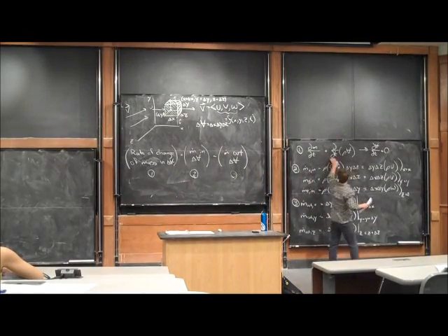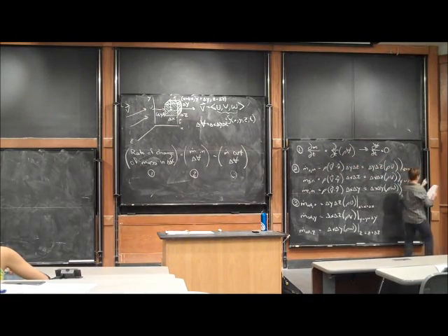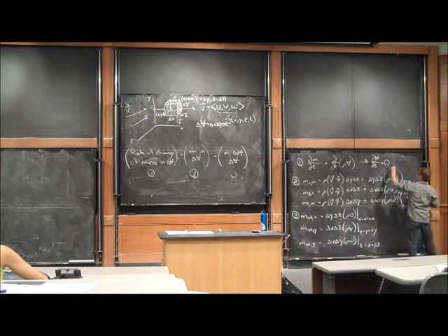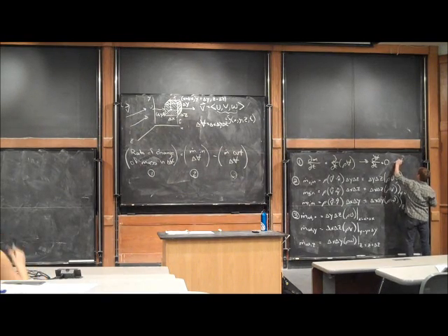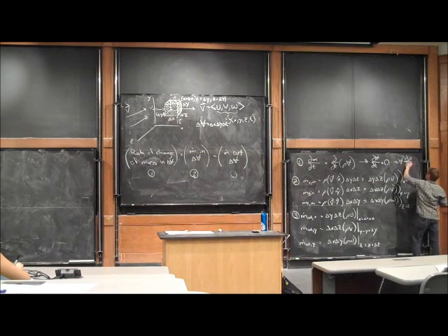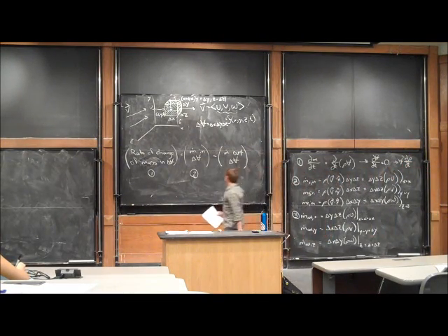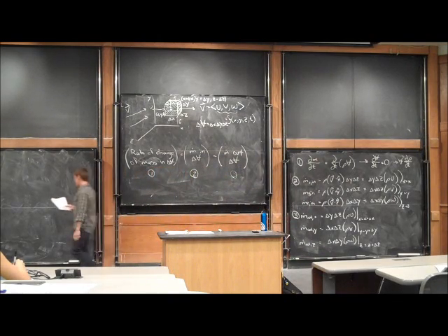dN/dt, which is d/dt of rho times V. Because V is not changing with time, we can simplify that down to V times d rho/dt. So V I defined here as delta x, delta y, delta z. So the first part of our equation, which is the rate of change, is delta x, delta y, delta z, d rho/dt.